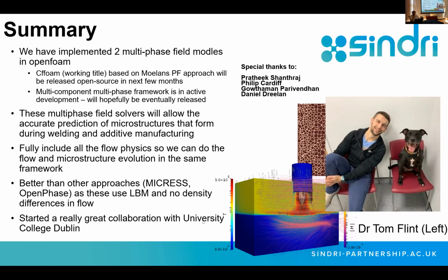You can do it, and if it's isotropic, that's a very good thing to do. But if you have anisotropy and dendrites growing, then you'd induce artificial texture. I can't remember, but you can show that just 10 phases in a cubic domain is enough.